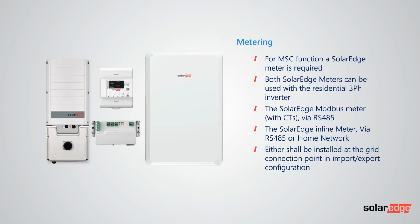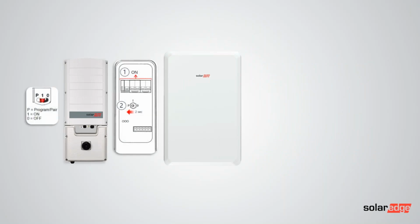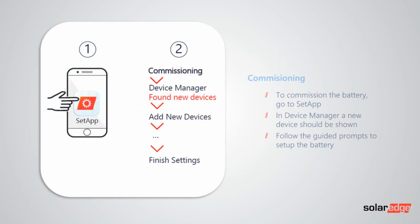Because there's a battery, now having a meter also becomes mandatory, because the inverter needs to be set up in MSC function, so maximizing self-consumption. The meter obviously needs to go in the main switchboard. You can wire the Modbus meter RS485 or the inline meter RS485, or that can also communicate over Ethernet. And when it's all commissioned, just make sure it's obviously in import-export configuration. And then once it's all in, that really is the wiring and setup. Then just go through the normal turning everything on procedure, and then commission it through setup. So it is really, really simple now to add those batteries to those 3-phase inverters.